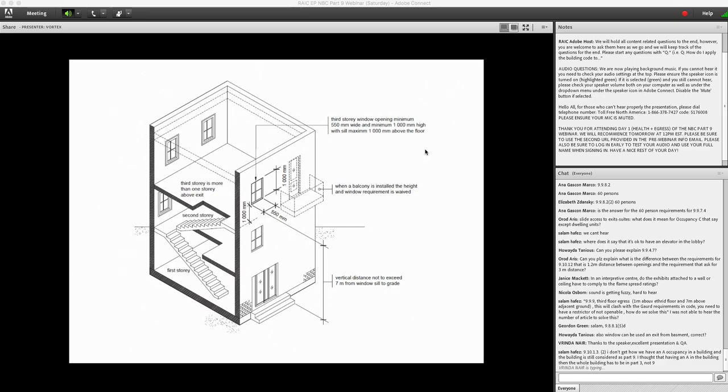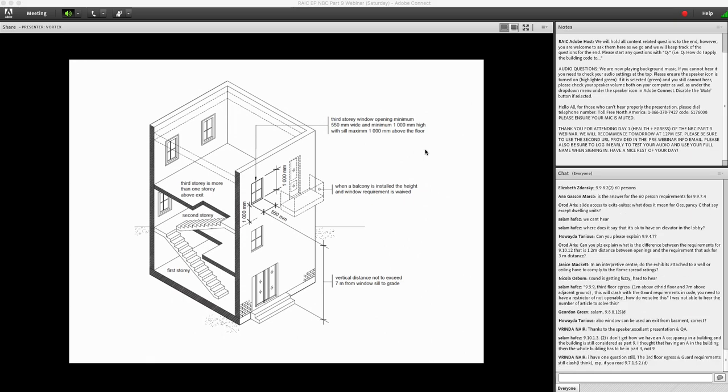Yeah, so back to the question on where the attic separation extends to the eave. If you fire separate the attic from the story below, and the fire separation extends to the eave, then the whole idea is that you have a construction that is able to limit fire spread.